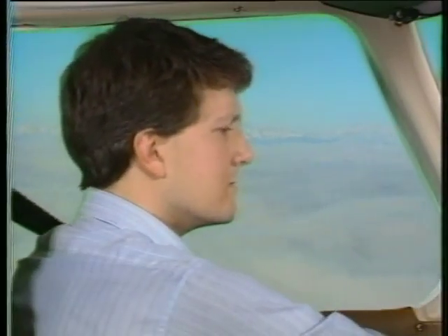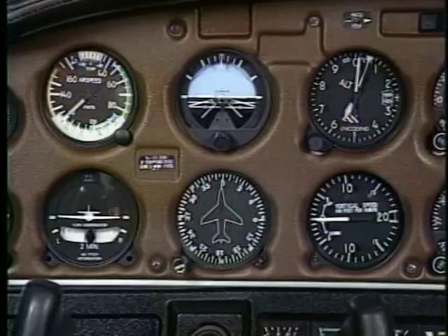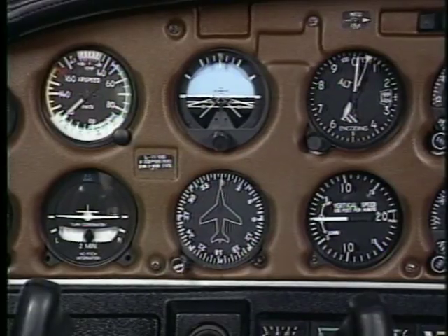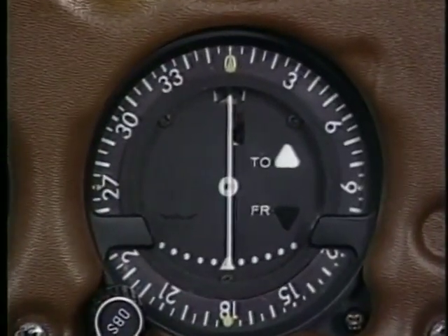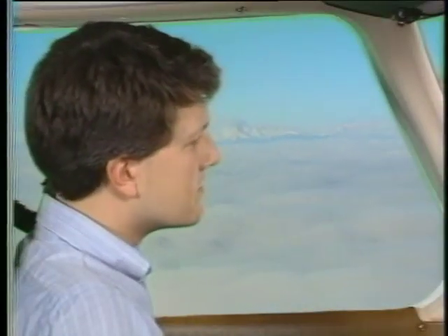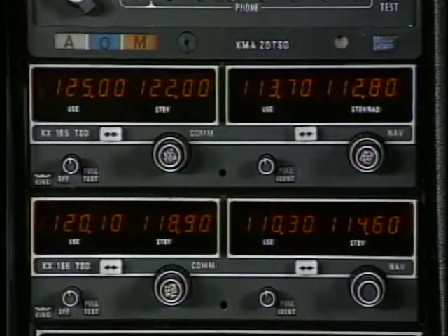The ability to visualize your position is one of the most important IFR skills you can develop. It makes IFR navigation much easier. With that in mind, let's review some of the basics of VOR navigation as they relate to IFR flight. We'll begin with this clearance from departure control. "Warrior 312, 5 miles northeast of Jackson VOR, intercept Victor 77 and resume your own navigation."